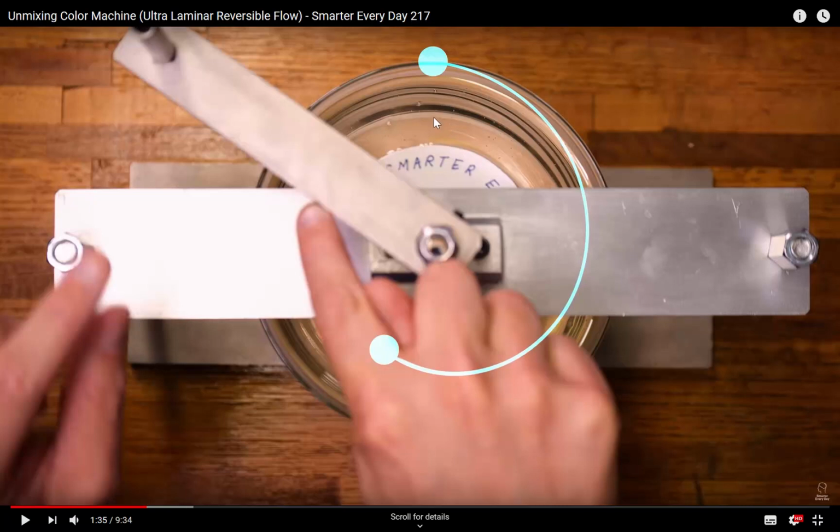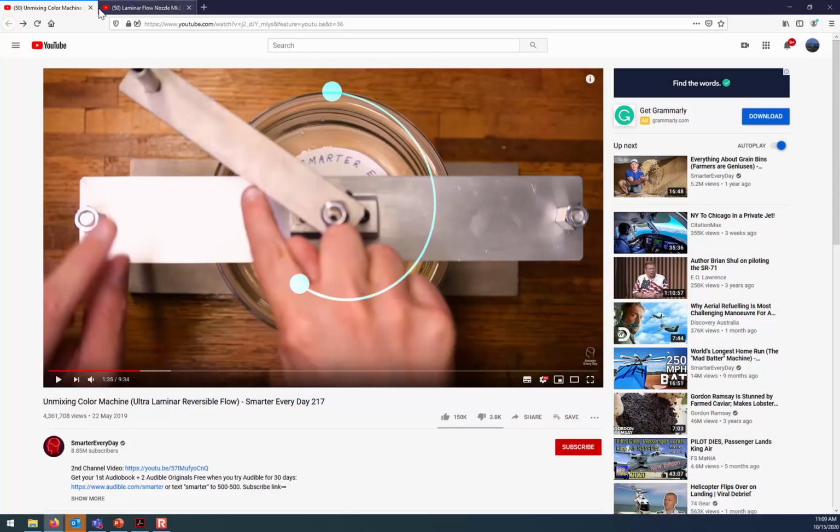And then he mentioned the shear thinning. The fact that there were certain times when he was rotating it a little bit faster than others caused the viscosity of the fluid itself to change. And so he described them as striations, or you could see little ring waves. And that was related to the fact that the rotation speed was a little bit different as he was going through it. So that's, I think, an interesting illustration of laminar flow. And let me show you another.